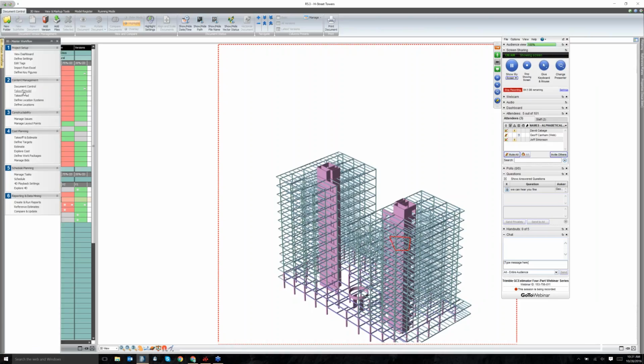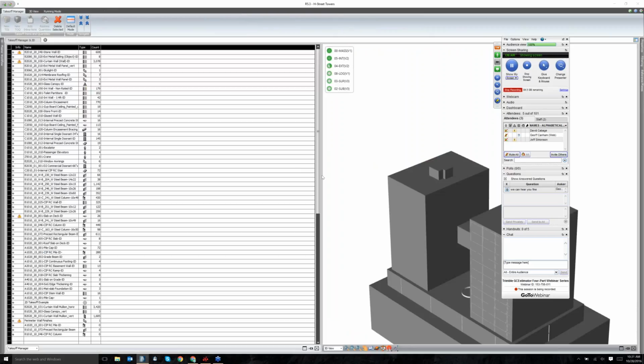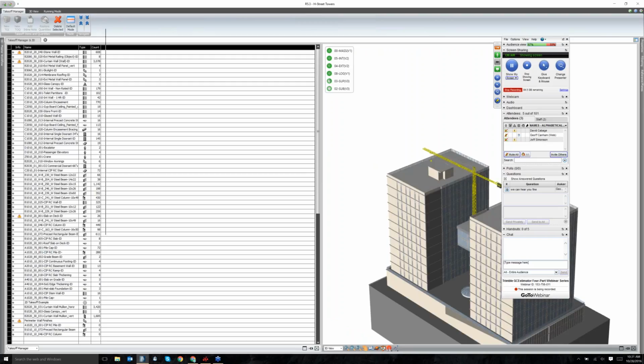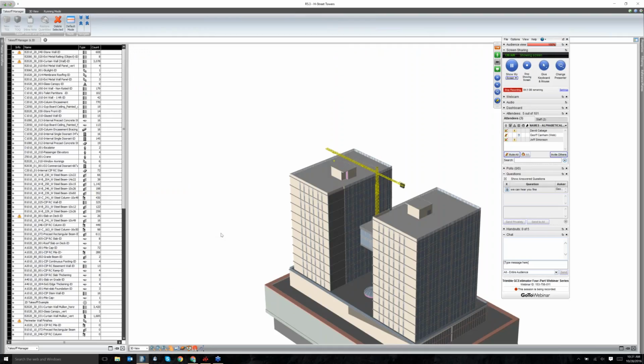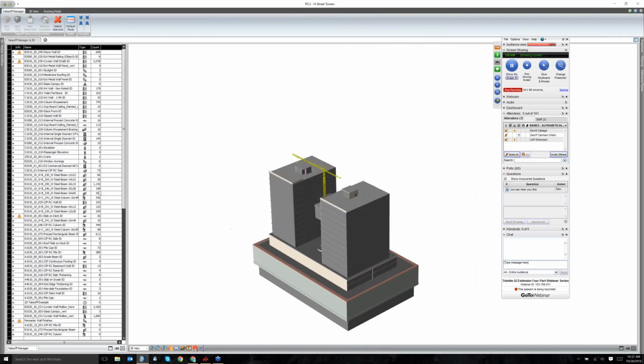So let's transition to our model takeoff view. And in this particular view here, or module, if you will, we call it TOM. Affectionately call this TOM, Takeoff Manager. What Takeoff Manager does is basically analyze all the elements within the project and quantify them. It basically fills it with virtual water and analyzes each element, and the moment that it knows it's a slab, it will give you the quantities that you need to price a slab, or when it identifies a door, it'll give you the quantities that you need to price a door.